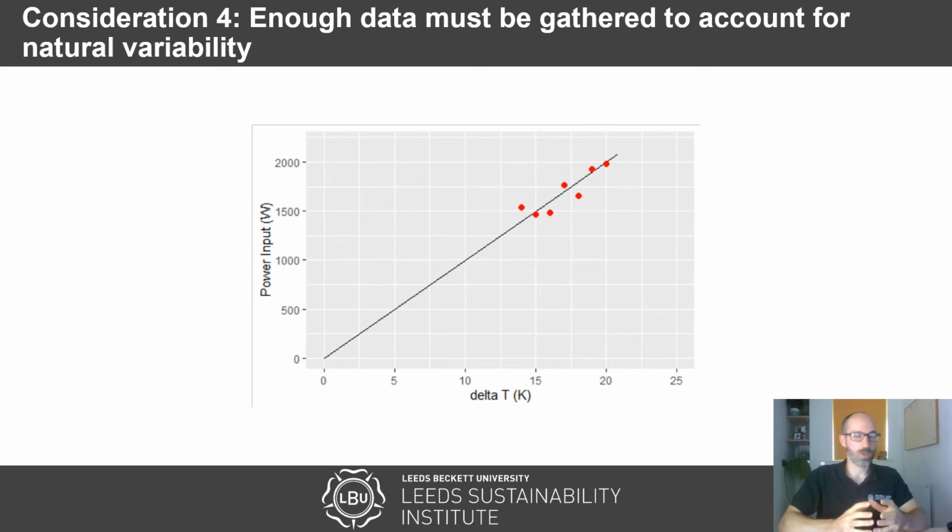And of course, if you were to just do the coheating test for 1 or 2 days, there's a pretty good chance that you will not be able to draw this line perfectly. From our experience, 14 days would be the minimum to get an accurate coheating result, but the more data the better. And also, if you get more data, you're more likely to have a variety of delta Ts, which helps to plot that line with great accuracy. If you do end up using less than 14 days of data, essentially you can still get HTCs, but the uncertainties on those values just end up going up and up and up to the extent that they can become somewhat useless.